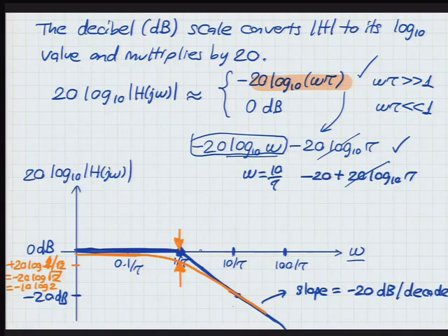If you look at the logarithm of 2, does anybody know? 0.3, okay. So this is going to look like negative 3. This is the biggest error you can ever get, and this is negative 3 dB, which in the linear scale means 1 over square root of 2 rather than 1.